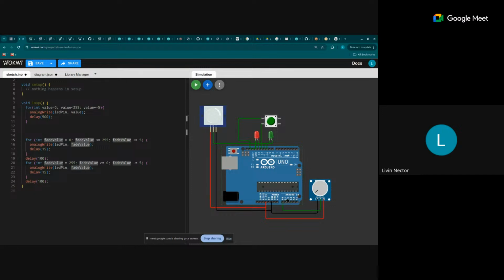The thing is, all these analog pins are by default input pins, so it doesn't matter. Only these other pins you have to be careful about, whether they are input or output, because these analog pins are the input pins over here. If you want to generate analog output, you generate that using PWM pins. These are ADC, right? It converts analog to digital, not digital to analog. So for analog things you don't have to worry, but you can also set pin mode to input. It's fine.